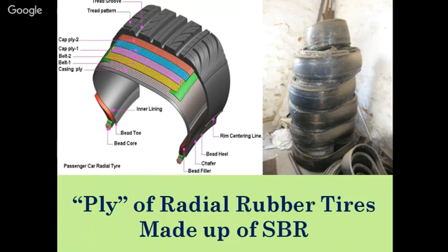In this research, there are two components. One, we have developed interlinked concrete blocks, and second, we have developed viscoelastic energy dissipator links. So here we have developed strong concrete blocks as well as weak viscoelastic interlinking elements. When the earthquake force comes, we provide the initial rigidity to the material.